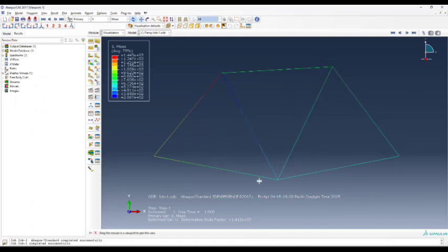Okay. Now I just want us to be able to get to this point and for us to feed loads, to feed boundary conditions, to feed material properties, and for us to be able to get some output of deformation outside. So that's basically what we did today by hand in the FEA hand calculations. This is the output. This tells us at what node displaces by how much. And this is obviously undeformed. This has not moved. This was a restricted one. This was a restricted one. These went down. This went down. But that's basically what we're looking for.